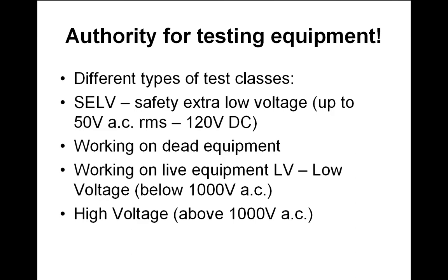So again, you would need a whole set of different authorizations. The normal Sparky, the normal electrician, will be okay to work up to 1000 volts on live equipment if it's required. Sometimes, for example, when you want to see whether there's something wrong with the three-phase motor, one of the things you might want to test is, do I get the voltage at the motor? If the motor is running, what are the readings? Once it draws a current, is the voltage dropping on one of the phases for whatever reason? And obviously you can't do this on dead equipment, so you would do this potentially on live equipment.